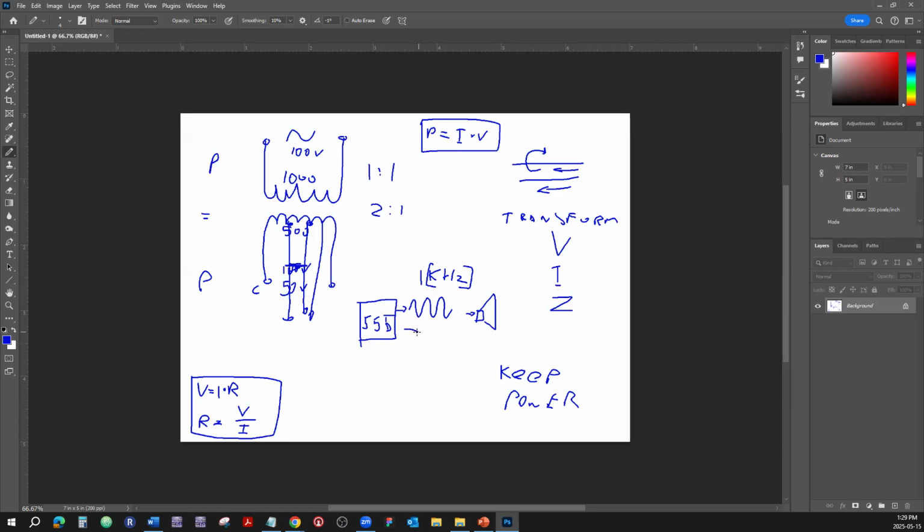But if you connect an audio transformer, an impedance matching transformer, between these two, those windings are going to work things out between each other. And we're going to have something that's called impedance matching going on through the impedance matching transformer. And if you do that, then the sound is just going to come alive. It's going to be quite a bit louder, if I could say that. All right. So we're using the transformers as impedance matching devices.